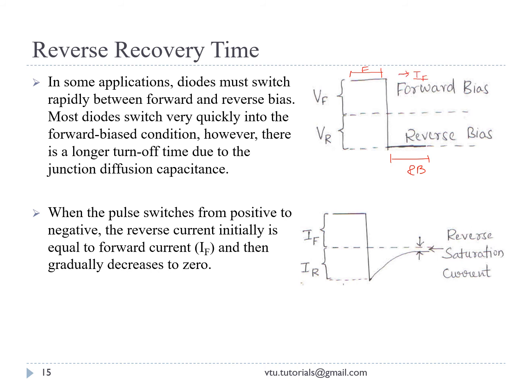Now suddenly there is a fall of voltage from forward to reverse voltage. When there is this fall of voltage, at this point the diode will be reverse biased. When the diode is reverse biased, we always know that the reverse resistance will be very high and there is some current called the reverse saturation current.